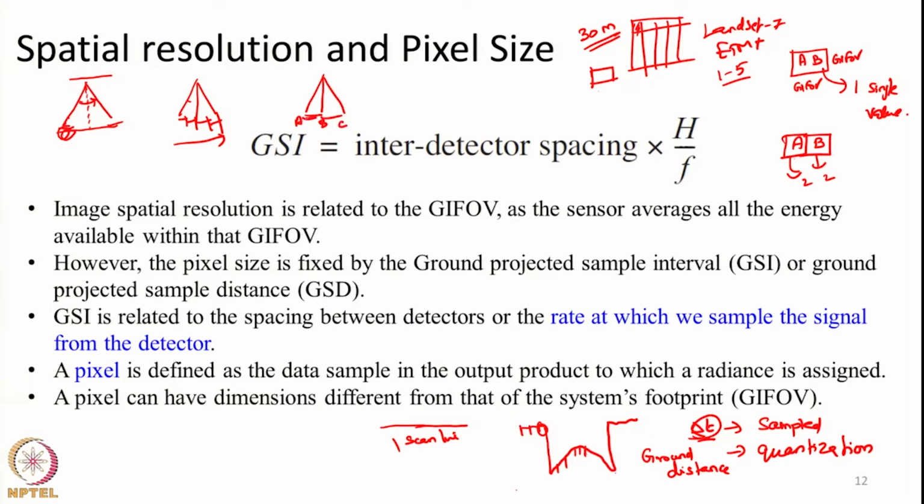So there is a certain distance the scanner moves for each delta t time period, and the sampling that occurs after each delta t and the corresponding ground distance moved by the scanner will determine the pixel size. Say at delta t the scanner moves a distance of 30 meters on the ground. So one sample is collected for a distance of 30 meters. Next, at 2 delta t, the scanner would have moved a further 30 meters in the across track direction, so another sample is collected.